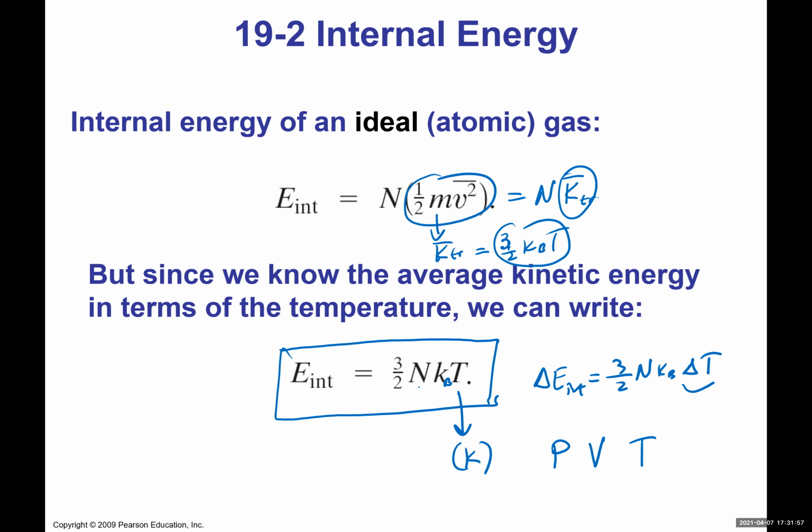Excuse me. And what we have here is that temperature is directly proportional to internal energy. So every time we have a change in internal energy, it right away tells us that there's a change in temperature. You cannot have one without the other. If you're changing the temperature, you're changing internal energy. If your internal energy is changed, that means the temperature is different, going from state 1 to state 2, for example. That's an important thing to remember, because when we get to the first law of thermodynamics, we are looking at internal energy relative to some other quantities, which we will see.